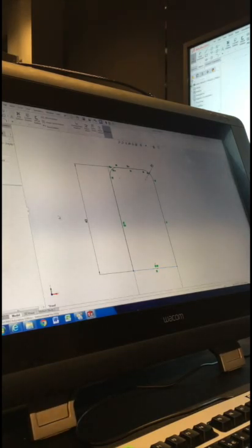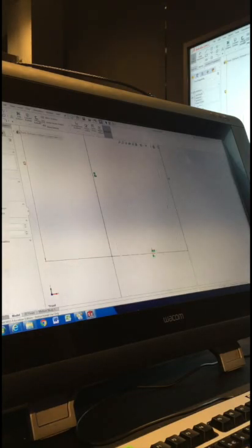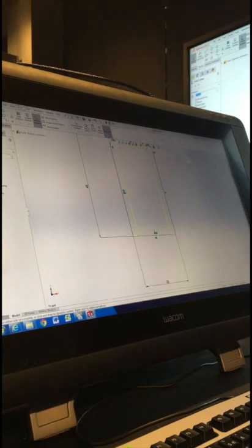Now when I try the offset again, this time those yellow lines go all the way to the bottom. Got to make sure I turn off change construction geometry to base. So I turn that off. I don't want to change anything to construction in this one. Now, I did also accidentally have cap ends ticked, which works because what that's going to do is add a little line segment to this bottom edge.